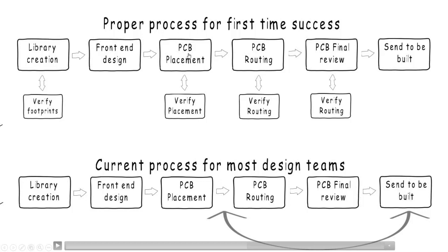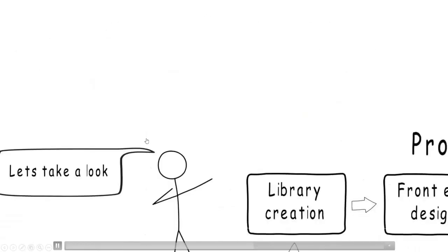You can get your supplier involved early, so even during the placement, critical routing phases, you can have them verify your design. Yes, there's going to be a little bit of time delay in there, but it's better than waiting till the end and finding those issues and then having to go back and rip up a completely routed board, which is definitely more time consuming. All right.